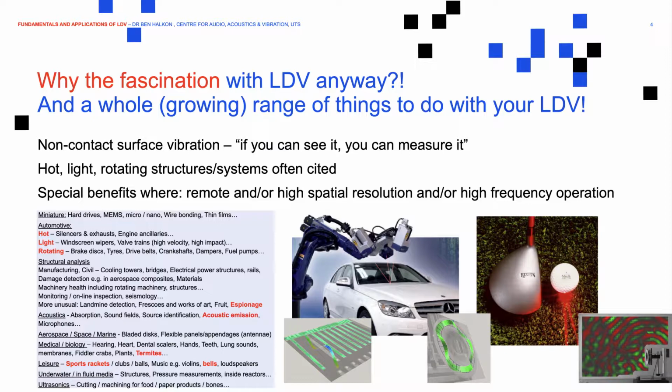Contacting transducers more often have some kind of signal processing electronics within them, so you can't stick them onto the primary exhaust cylinder output. Light systems, it's a no-brainer. We add mass and stiffness to a light system by attaching a contacting transducer to it, and we change its characteristics. And rotating systems are everywhere amongst us. They power the world that we live in. Without them, we'd be completely snookered. Putting contacting transducers on them is not so straightforward.